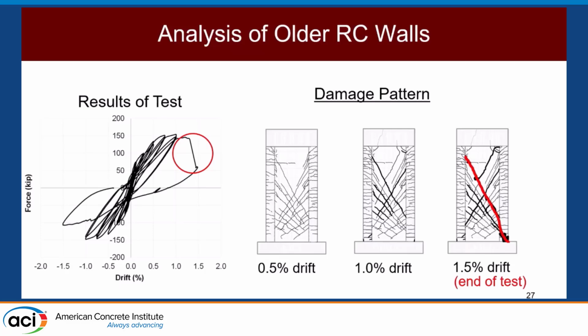So what happened is across this red line, the shear steel, the horizontal steel that we had in the wall, broke, and it could no longer carry that capacity. And so basically all of the force that the wall was trying to transfer got forced into the toe, because that was the only load path left for it. And so we had a very explosive shear crushing failure.